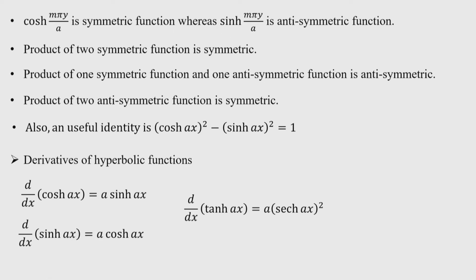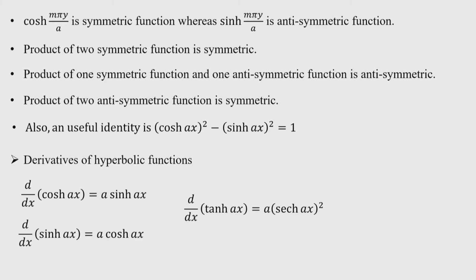That statement is very important for solving problems using Levy's method, because if the loading or deflection boundary condition is symmetrical, then there will be no antisymmetrical term in the deflection expression. So, naturally we can omit it from physical reasoning.